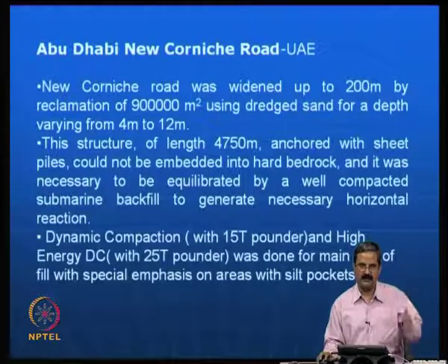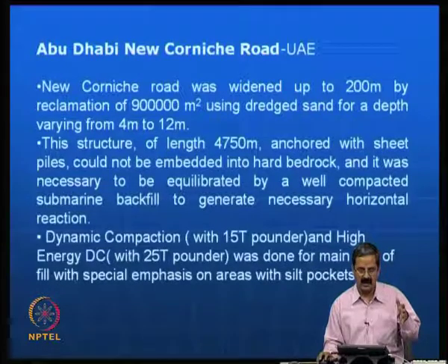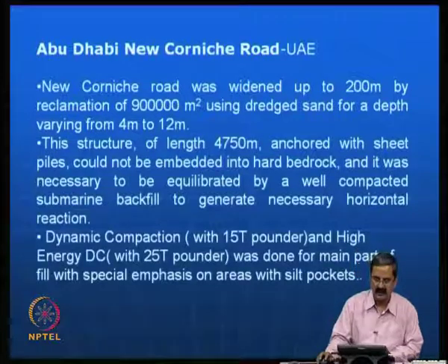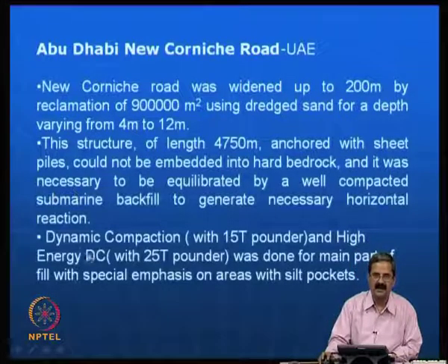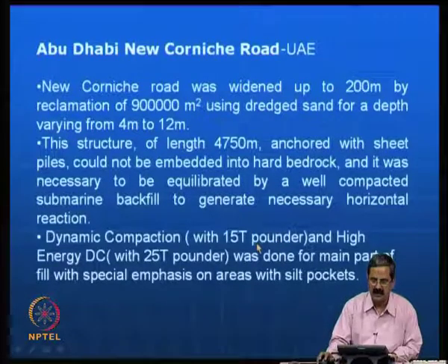So, for example, if you have a sheet pile wall with a less good backfill next to it, the load that comes on the sheet pile wall will definitely be much greater than in the case of a well compacted soil. So what they did was use dynamic compaction with a 15-ton pounder and high energy dynamic compaction.